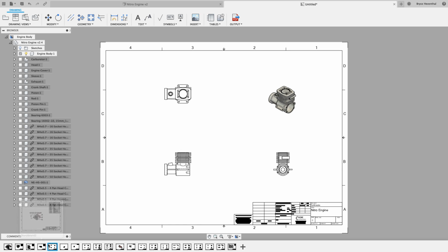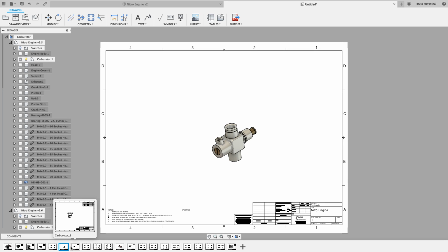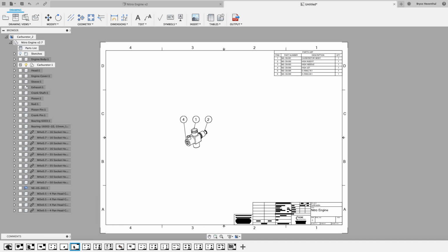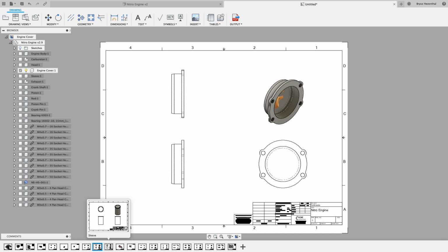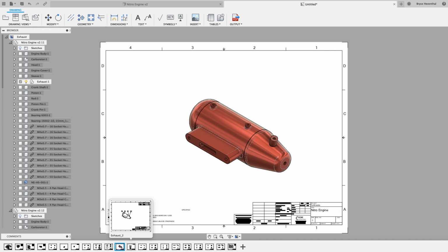And then, as you could see, after the exploded views, as I go through these sheets, it's just going to work down my browser, component by component. So if you look through there, it went to the subassembly, went to a subassembly, showed the BOM for that subassembly. Now it's going to go to the components, and so every component, it will lay out a front, top, and right in an isometric with the color on, and that's because that's how I set it up. So you see it goes component, component.